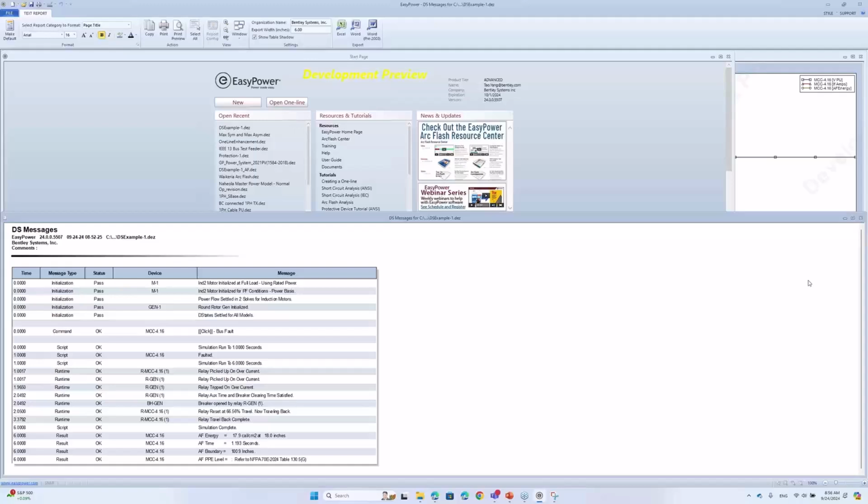So usually the excitation, especially the automatic voltage regulator, comes from the exciter manufacturer. However, the amplifier of the excitation system is usually equipped by the generator manufacturer. So you have to obtain data from both the generator manufacturer and your excitation system manufacturer.